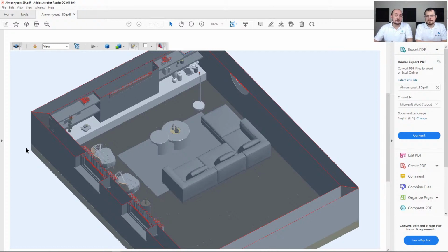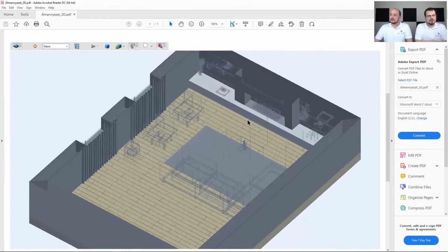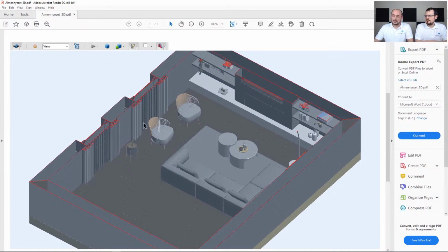So this easily you can just save the model into a PDF file, copy that PDF file onto another device like another computer, use the free reader and open up the model, and you can just look around the model, turn it around, create a section if the interior is important, then discuss the layout with your clients. Again, a very good way to keep your clients up to date.